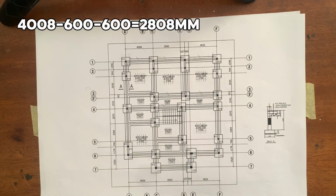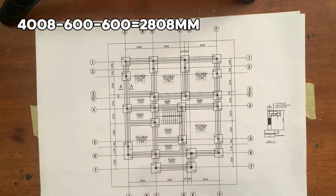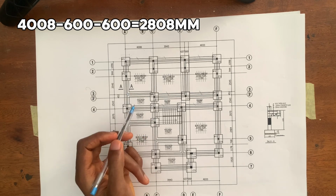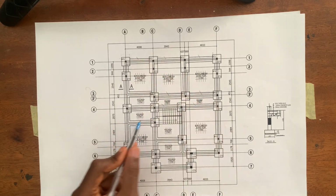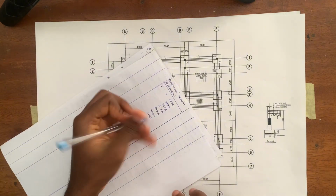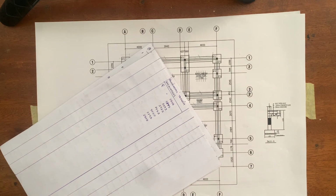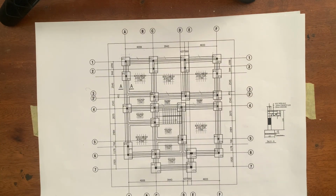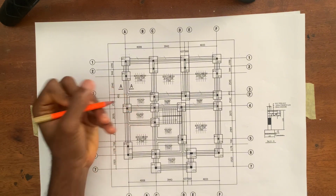So 4,008 minus 600 for half of base type 2, and then 600 for half of base type 1, is going to give me 2,808. So you see that it is the same thing as what we have here. So we are now going to record 2,808. So we measured for this part.